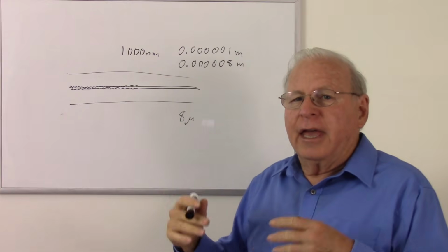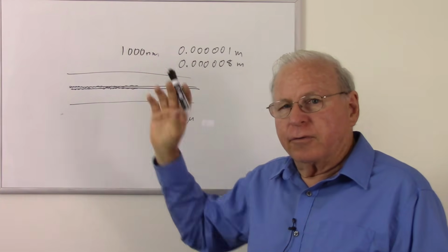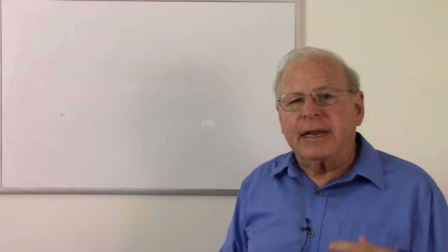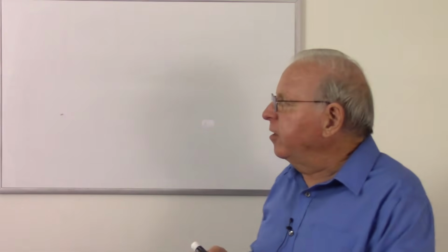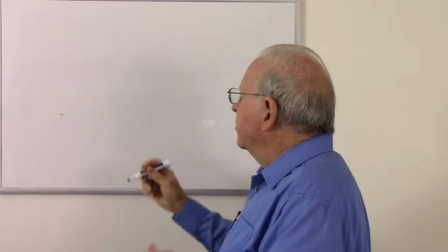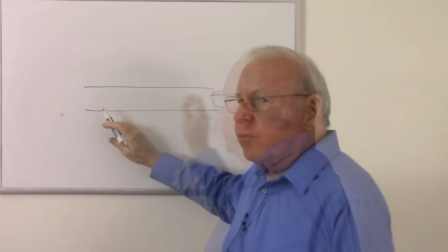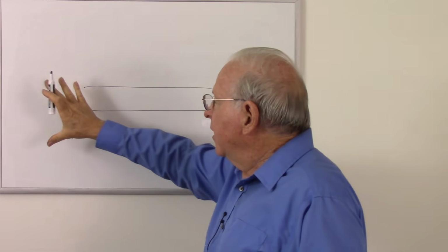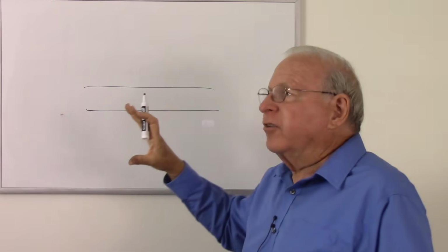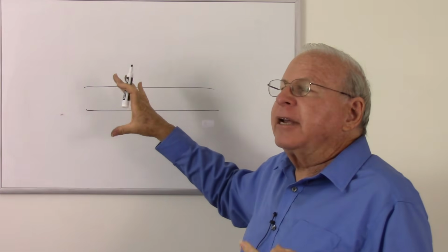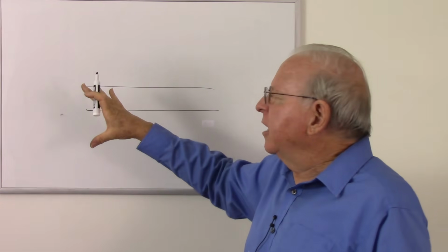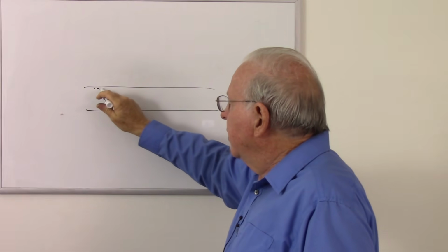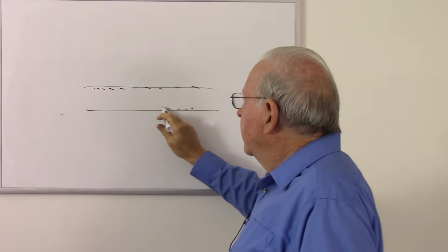It works just like a radio waveguide, which we'll talk about down the road in communications. But there's yet another way to mitigate it, which is a compromise between the two. So I'm going to start out with a chunk of glass. Let's make a glass tube of one index of refraction. But what I'm going to do is now put that in a chamber, and I'm going to put in some gases in there. I think they're germanium tetrafluoride and silicon tetrafluoride gases, and they're going to deposit a soot on the side.